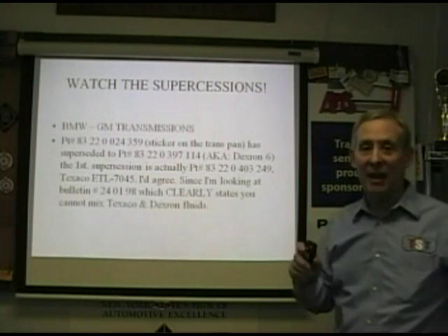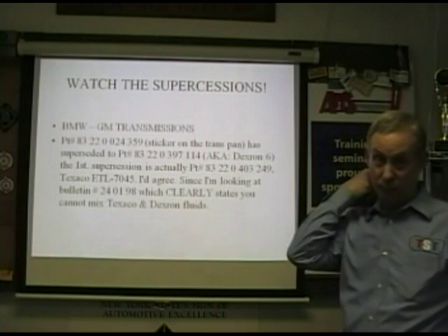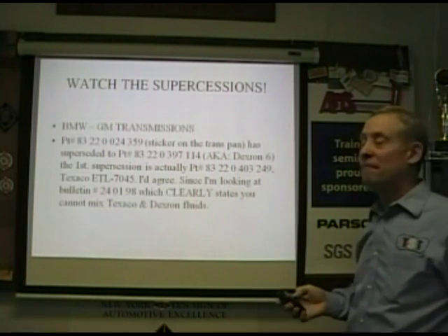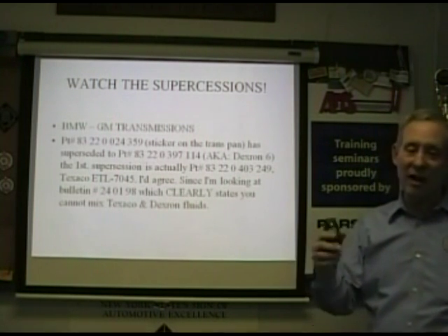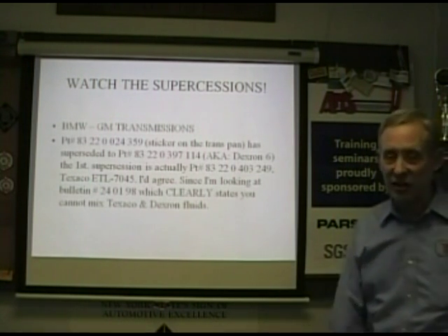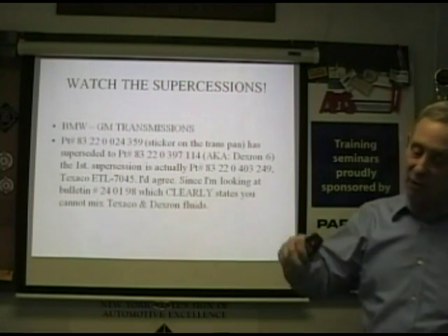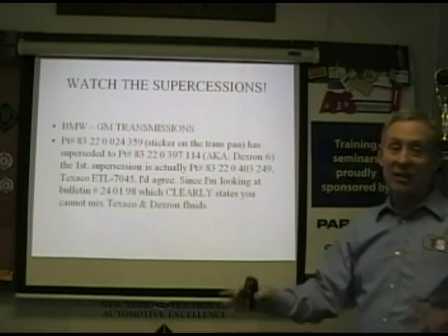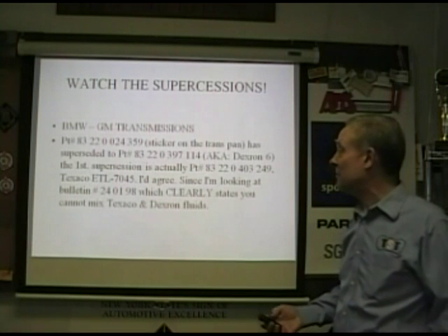So you have to be absolutely sure that if you switch it over to Dexron, which you can do, my personal car has it in there, my wife's car has Dexron in it, you must flush it a few times. If you can't get it all out of the torque converter, you flush it, run it a little bit, drain it, put more in, and do it again. Take it for a ride, make sure everything moves and pumps itself out, and drain it again. You may do it 2 or 3 times to make that switch.